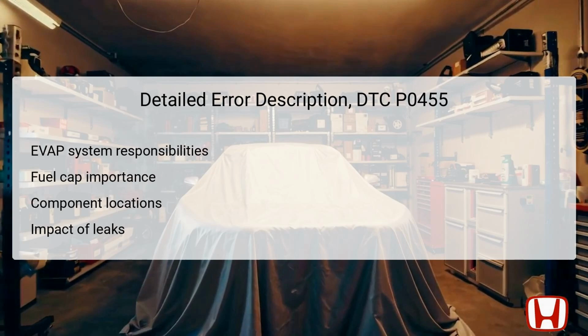The fuel fill cap, located on the fuel filler neck, serves a dual purpose. It not only seals the fuel tank, but also contains a pressure relief valve. The presence of leaks can lead to situations where excess pressure or vacuum damages these sensitive components. This can ultimately affect the vehicle's performance and compliance with emission standards.